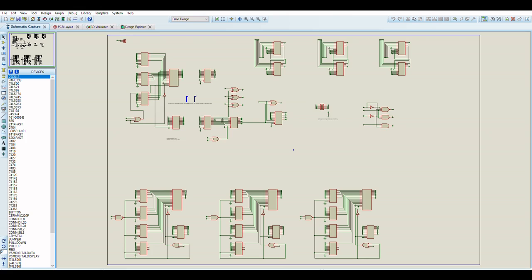This is the character screen RAM and associated color screen logic. The character screen is relatively simple. We have the same arrangement of 3 planes, 3 bits for the character definition pixel, and we have the same arrangement for the flips. So depending on if it's horizontally flipped or not, it uses the same shifter mechanism that we saw in the sprite logic to decide whether or not to horizontally flip.